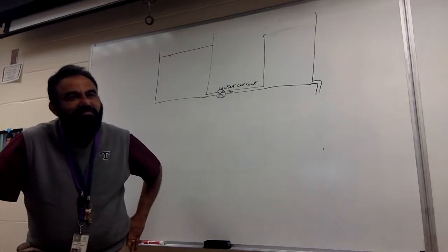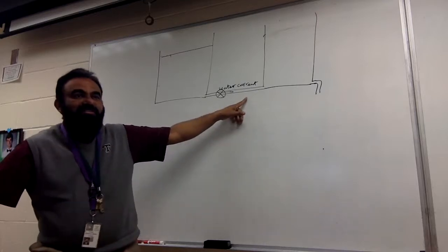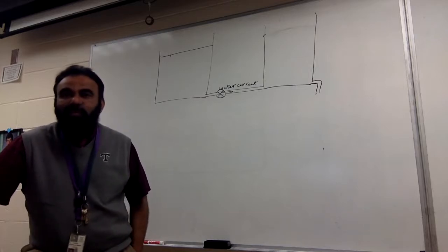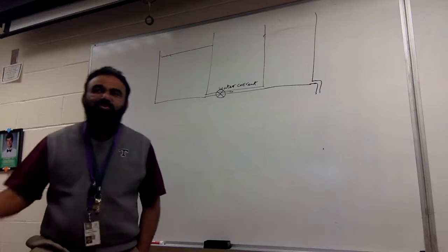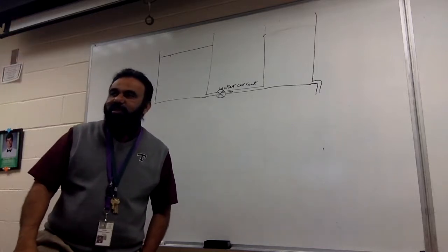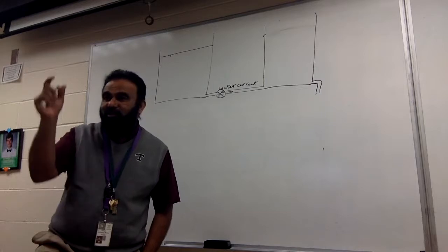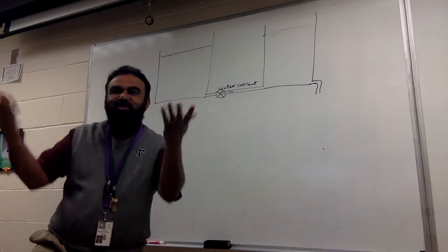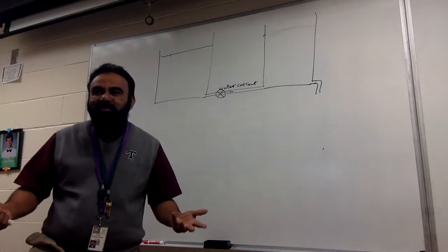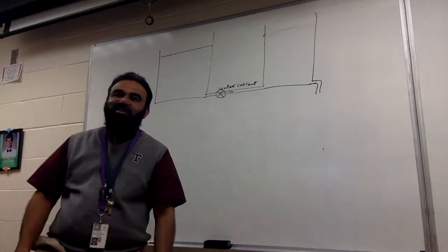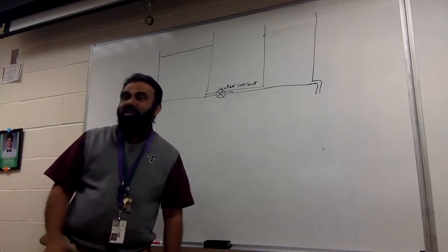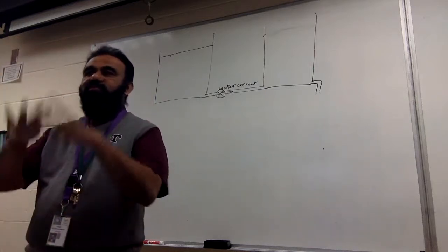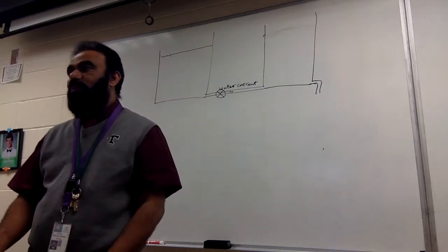Add more turbines, more energy. I'll add more turbines here. Yes. In fact, that is one thing you should understand. If you add more and more turbines, you're restricting the flow rate completely. Have you seen those wind turbines? How many blades do they have? Three. And that too very narrow. Why can't they just fill it up with 20 blades? Then it'll stop the whole flow, which means it won't spin. You can't just fill it up with blades all over the place, because you need to let it spin and you need the flow continuously going on. Once you block the flow, it is not going to spin.